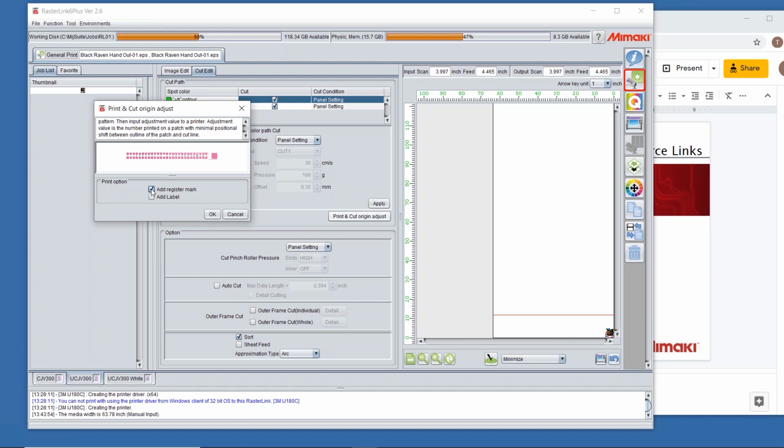Also be aware on solvent printers that the solvent ink and PVC themselves have a shrink and expansion rate of about 0.5%. So it's very common, we'll get a call that the cut isn't going right. And the problem is really that what's printing is not the size it was on the PC. And unfortunately, that is the nature of solvent printers. The ink does attack PVC. That's how it etches into the surface.